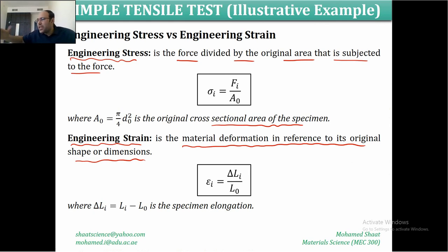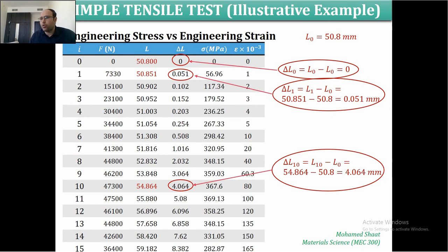But in some other application, we have to use the material within its plastic behavior. We need the plastic behavior of the material. In that case, we have to deal with the true stress, true strain behavior of the material that had been defined over the last slide. Make sense? This is simply what distinguishes engineering stress or strain from true stress or true strain.